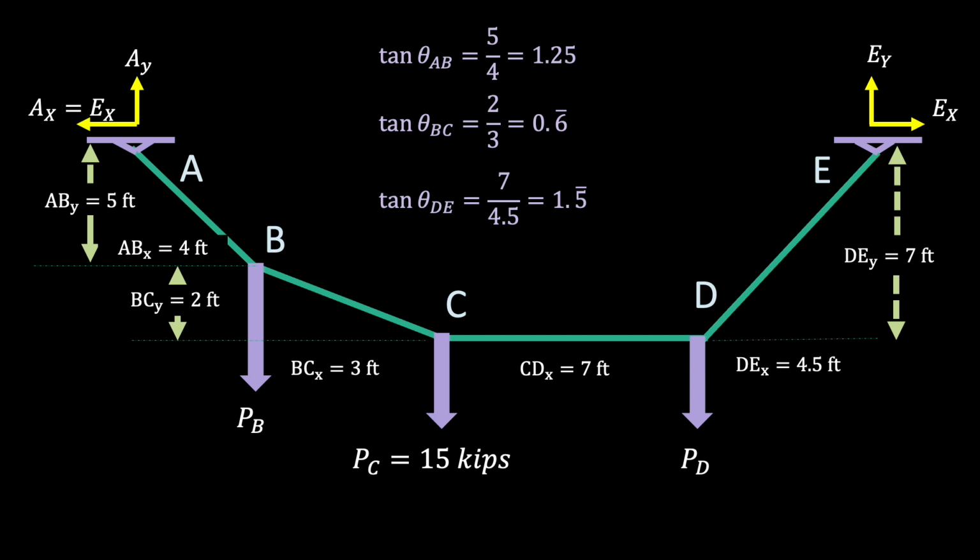That's because the more sloped it is, the higher the proportion of that section's tension goes toward the vertical component. So the steeper the cable segment is, the larger the overall tension in that segment becomes.